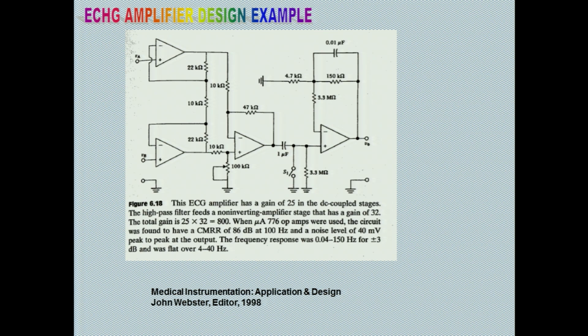And then everybody remember CMRR, common mode rejection ratio, you want it to be as high as possible. We are going to use 741s in the lab, correct. What is the CMRR of a 741, anyone remember? It is more than 80, that is good enough for our purpose, 90. So 86 dB and more.